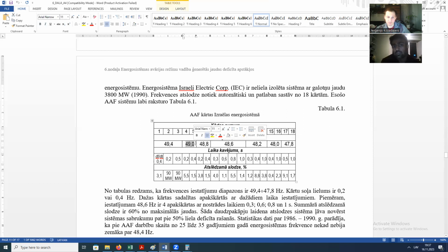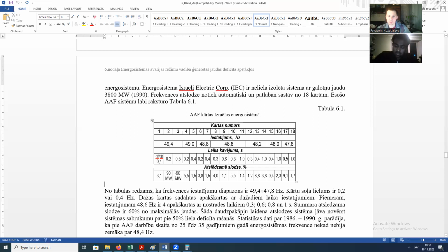There is a starting group and one more parameter that is quite relevant. To be true, it is set everywhere, we just are not talking about this parameter. It is the speed of frequency decrease. So we disconnect the loads not only when we have a frequency decrease, but also when we have a high frequency decrease speed.